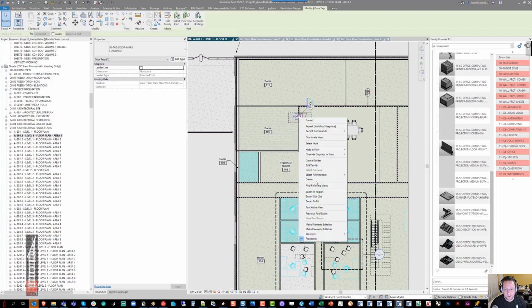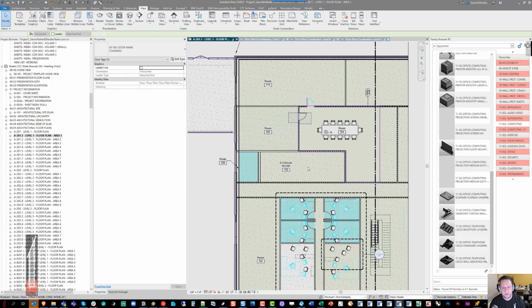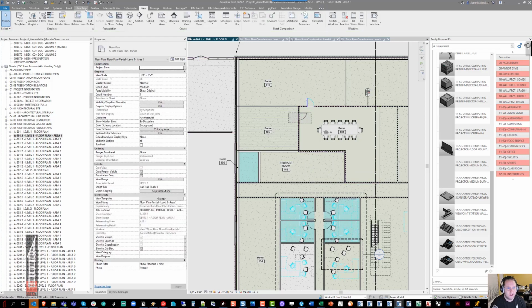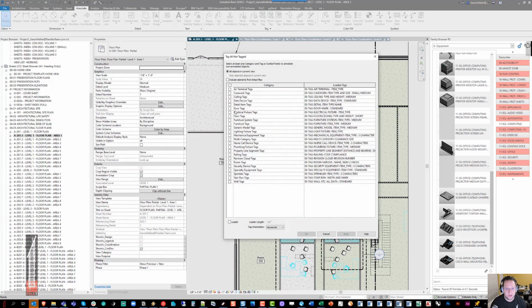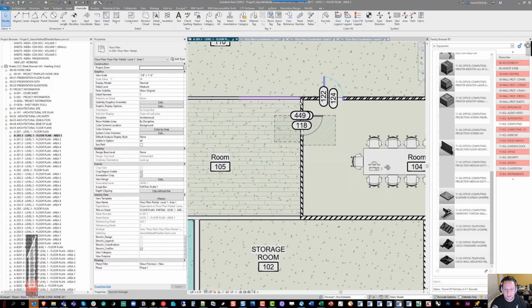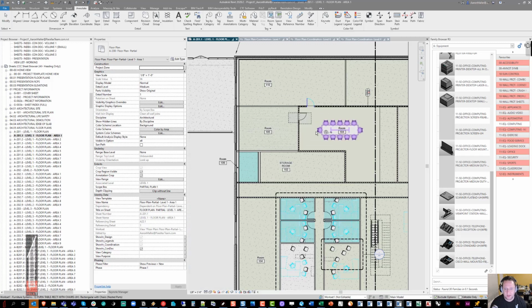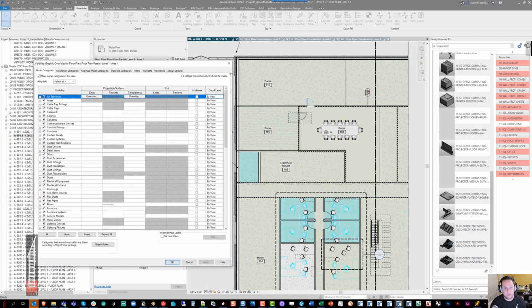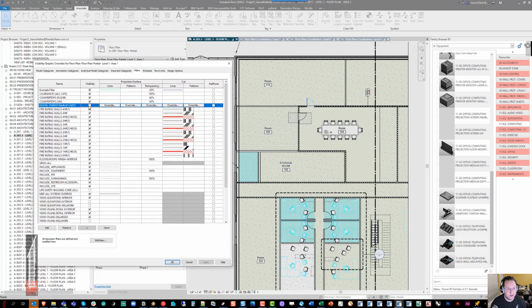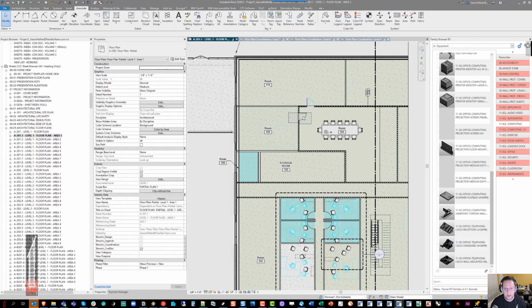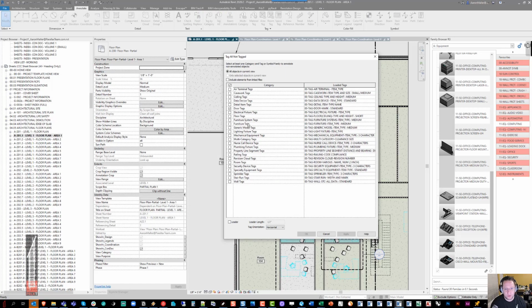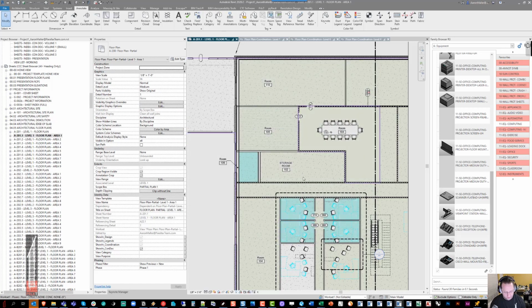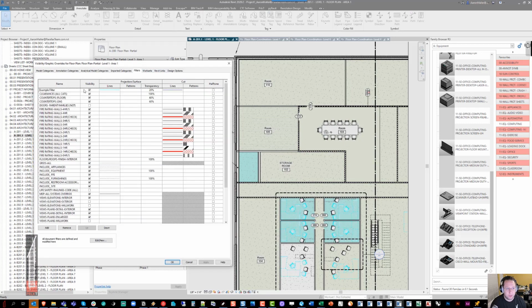So if we select all of the door tags in the view and delete them, you may recall that using tag all on doors would accidentally tag many nested door components. That's undesirable. Instead, if you go into Visibility Graphics Filters and uncheck the parent family's not filter, all those items will temporarily vanish. You can tag all doors, and then you can simply turn your filter back on.